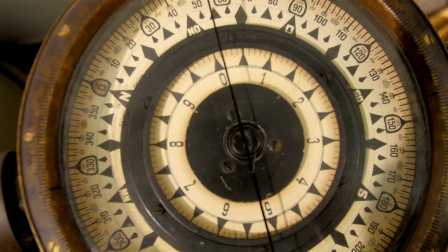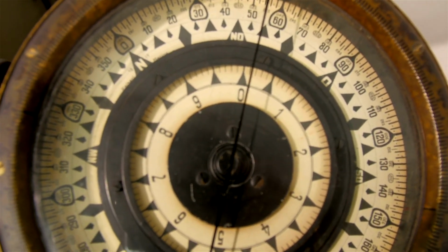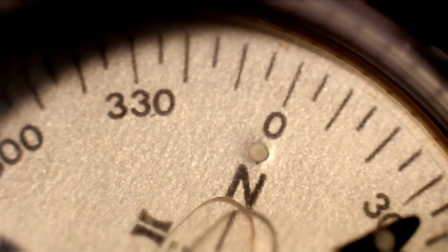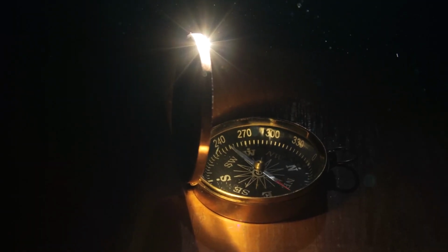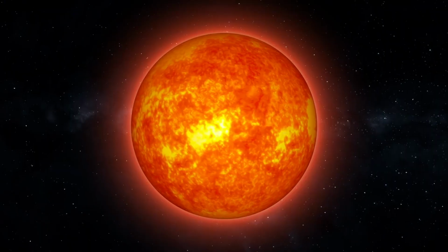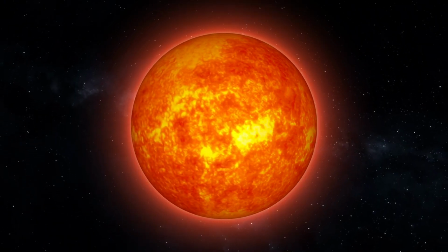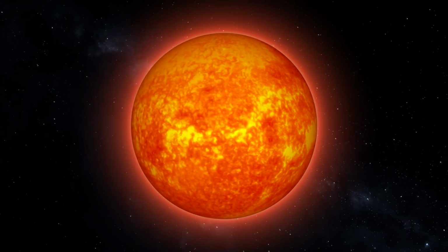You can also use the sun and celestial navigation techniques to check the deviation of your compass. Here's how to do it at sunrise. 1. Work out your latitude. 2. Make sure you've got a clear sky so you can see the sun. 3. Work out the sun's declination in your almanac. 4. Apply your latitude and the declination to the table to give you the true bearing of the sun at sunrise and sunset. 5. Once you have your true bearing of the sun, apply variation to give you the magnetic bearing of the sun.